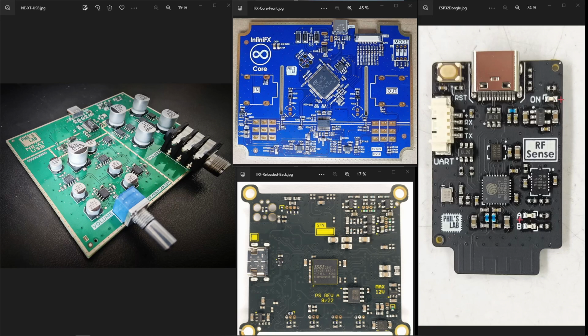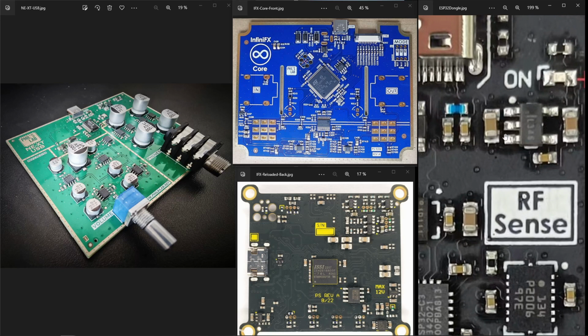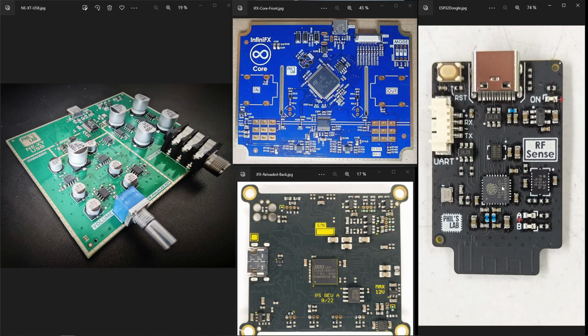On the right-hand side, looking in the top right corner, this is the LDO regulator with its surrounding circuitry. The reason I chose it for this design is because of its small size that has to fit on this board, its low noise, and the low amount of external required circuitry. This is in direct contrast to most switching converters, for example step-down or buck converters, which require a lot of additional circuitry.